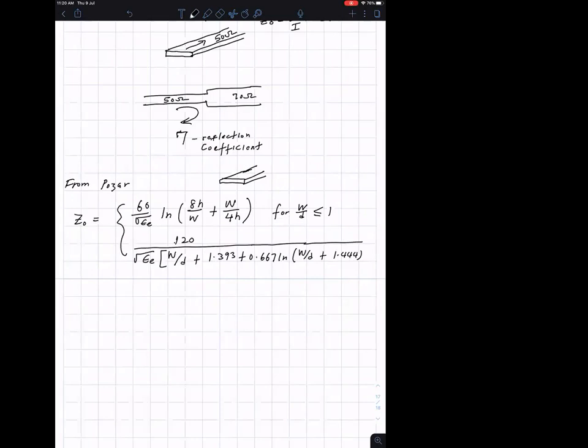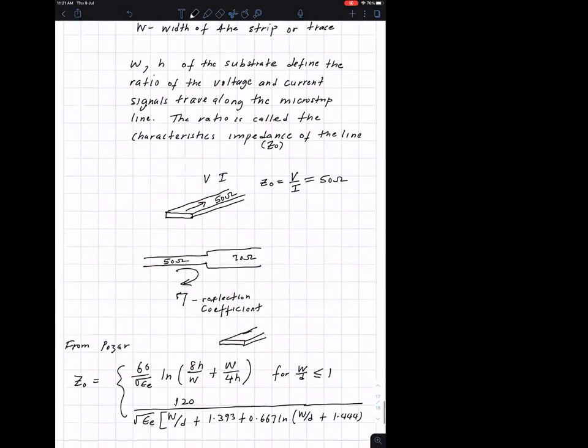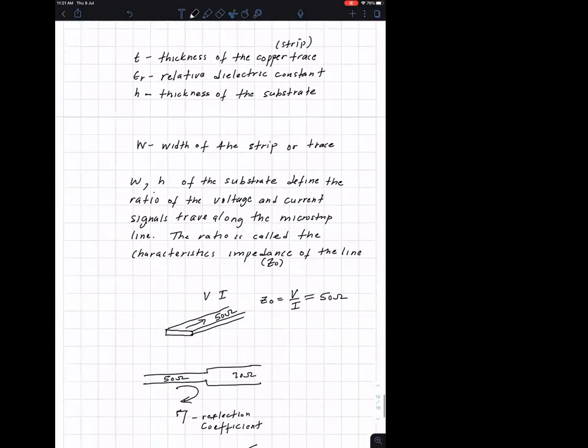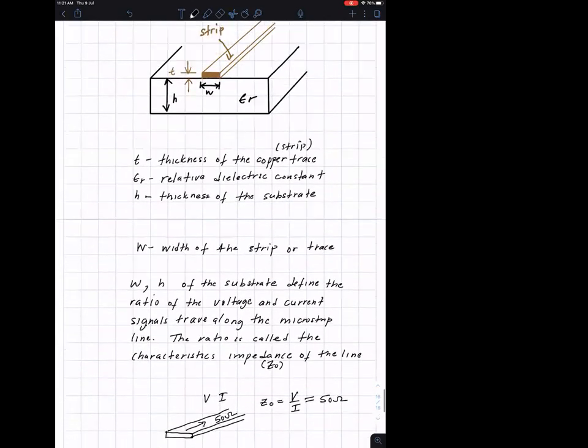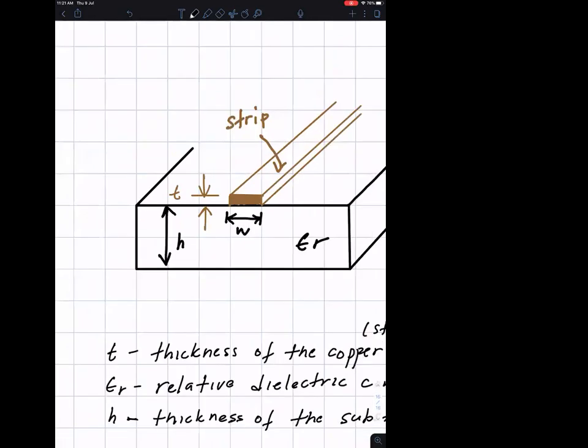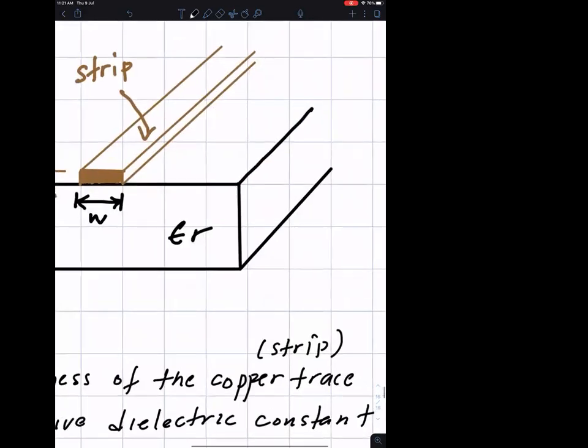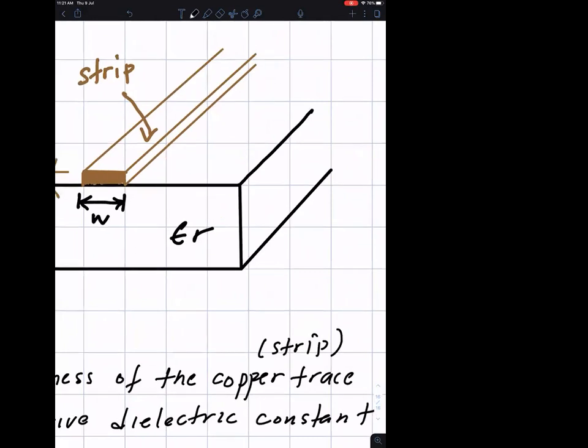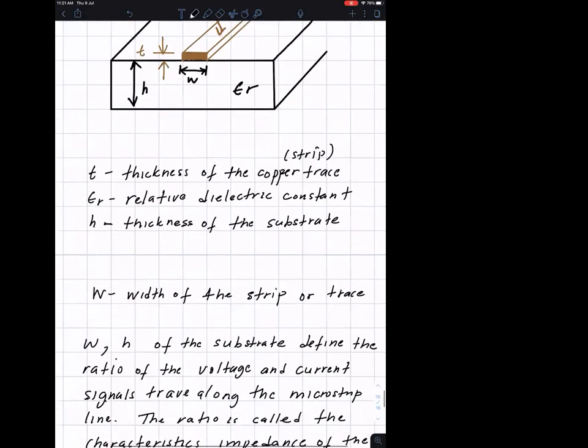As an engineer, you order the substrate. It is some particular substrate, and then you already design for that substrate. The substrate with particular age. But after design, you see it's not meeting your design spec. Then you go and analyze and see the vendors supply the wrong thickness, and then maybe the vendors supply the wrong dielectric. So that's why you, as an engineer, should have some idea about these things.